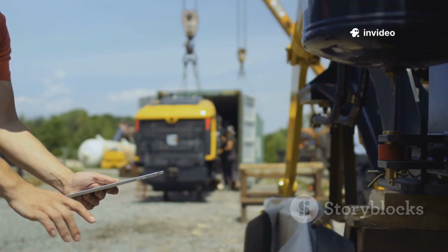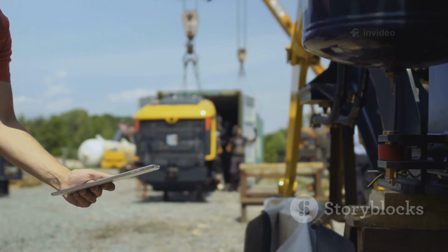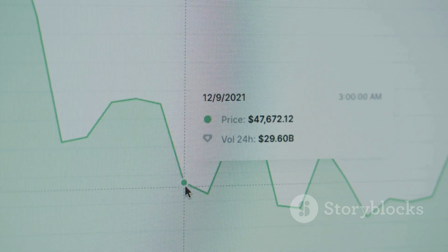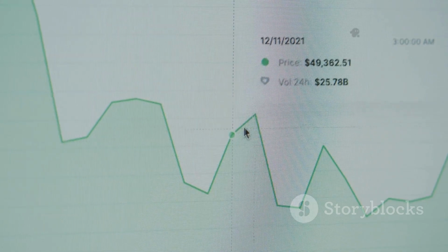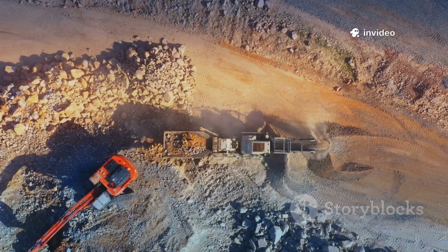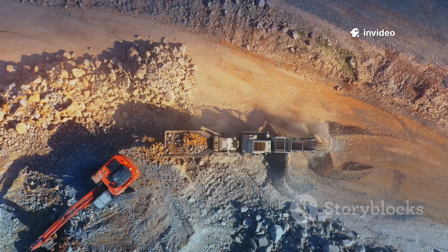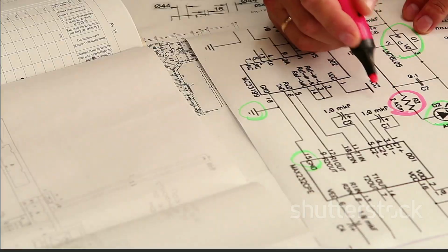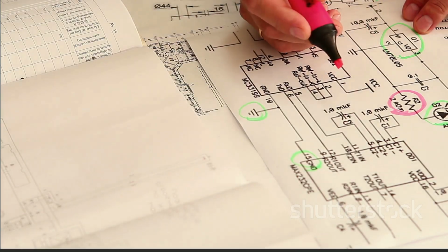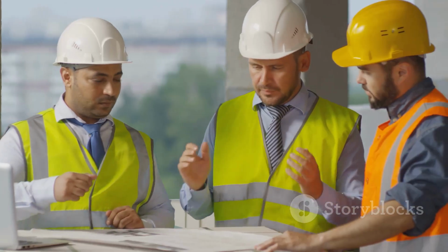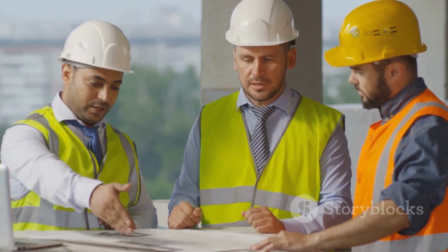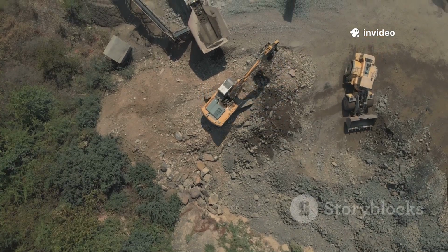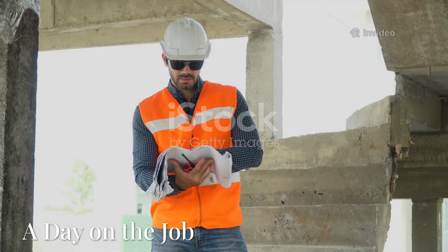The mass haul diagram shows if you'll end up with a surplus or deficit. If the curve ends higher than it started, you have waste. Lower, you need borrow. This lets engineers plan ahead, finding borrow pits or waste sites early and budgeting for the extra work. The diagram makes these costs predictable, not surprises. It's another way this simple chart keeps projects on track. Balance is the goal, but the diagram helps manage the mess when nature doesn't cooperate.